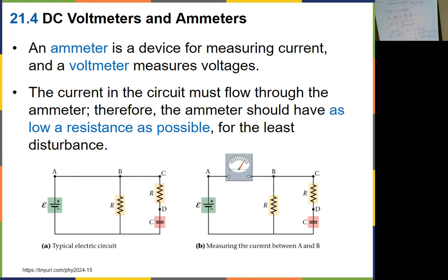That's why when you are using ammeters, be very careful, because the resistance is very small. If you apply any voltage across it, it will cause a lot of current going through it, and it will burn the fuse inside it. So occasionally, when you are given a multimeter that's not measuring the current, it's likely that the fuse has been burned, due to not so careful operation of it.